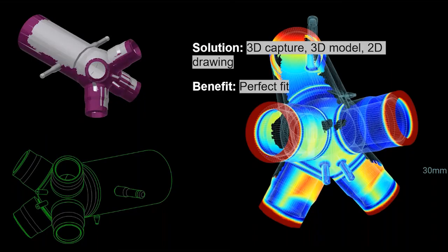That's a challenge. Inaccurate or missing measurements will lead to a bad design that can require hours of costly on-site adjustment when installing the new header in the next shutdown. Worse, it could delay the installation if the adjustments to be made are too critical. So using a 3D scanner here will solve these issues.